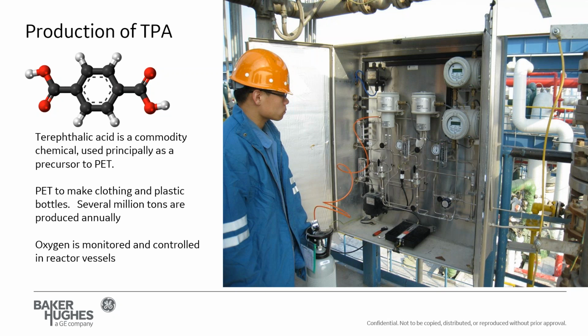So here again, we see a technician feeding the unit with a zero or span gas as a routine maintenance thing. We recommend calibrating it every 3 months or so.